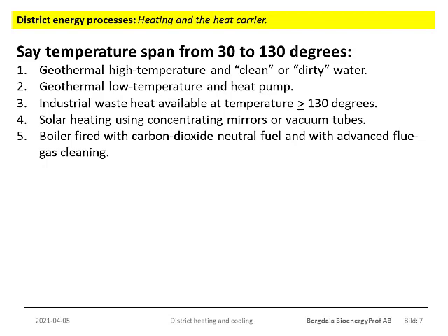Maybe you have access to geothermal energy, but at too low a temperature. In that case, you can use a heat pump to transfer the energy to the circulating water. If industrial waste heat is available at a temperature level above 130 degrees, you can use a heat exchanger.